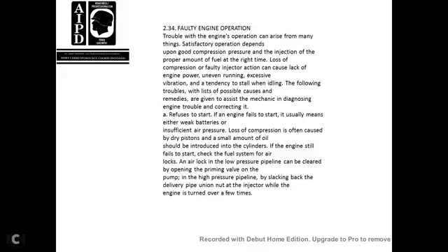2-3-4, Faulty engine operation. Troubleshooting the engine operation can involve many things. Satisfactory operation depends upon good compression, proper injection pressure, the proper amount of fuel at the right time, and no loss of compression. Faulty engine action can cause a lack of engine power, uneven running, excessive vibration, and a tendency to stall when idling. The following troubles, with a list of possible causes and remedies, are given to assist the mechanic in diagnosing an engine trouble and correcting it. One, refuses to start.